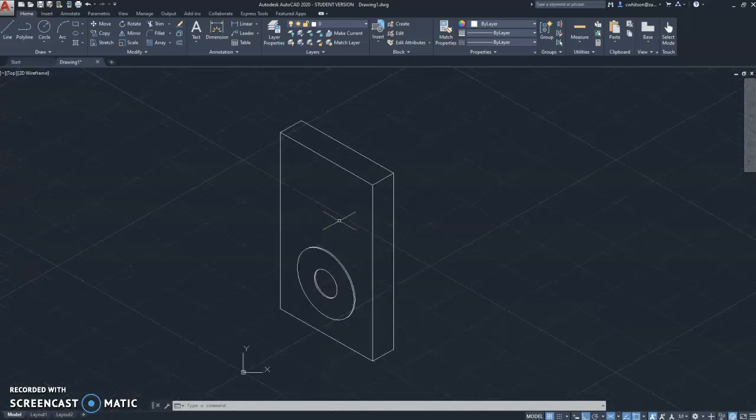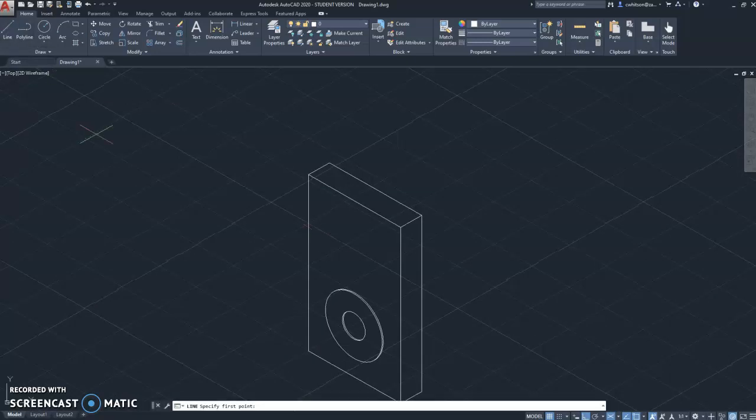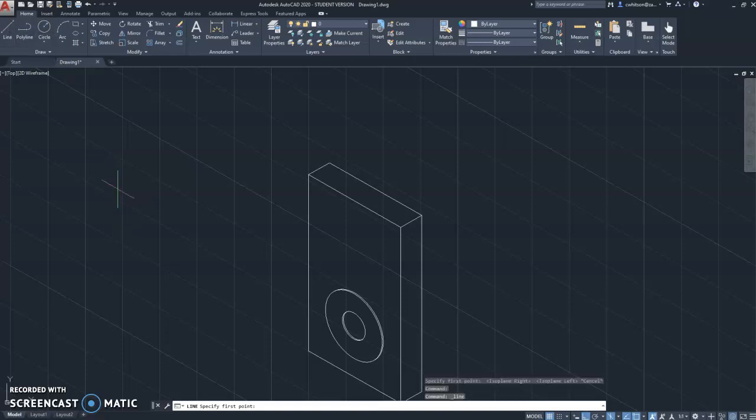Okay, and it has, I think I'll just draw it off to the side. I often do this. I draw things not in their final position, but somewhere else, and then move them into position. So the screen is just going to be a rectangle, or since this is an isometric drawing, a parallelogram. It looks like it has a width of 5.242 and a height of 4.